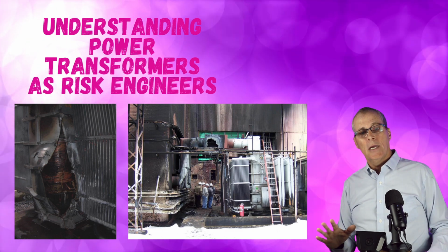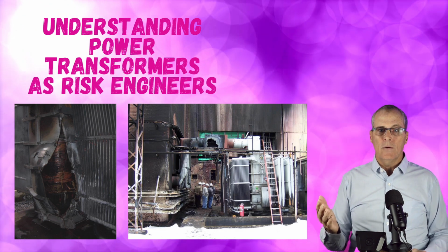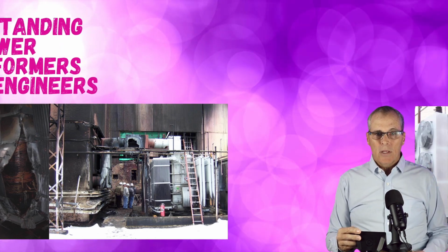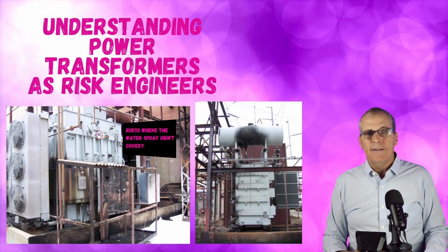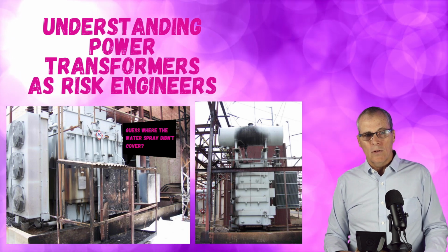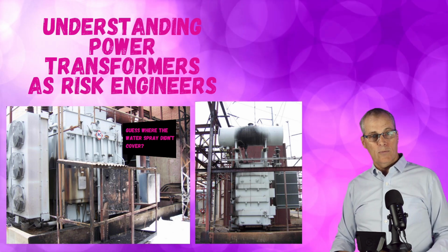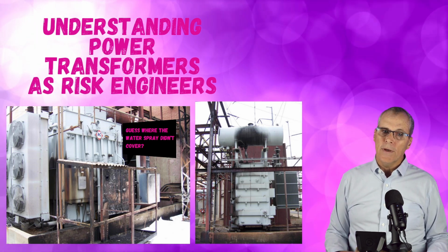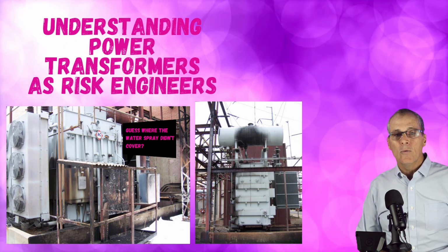But they're not trained well enough in that kind of firefighting, and I will admit that their training is don't shut off the protection. So this fire, you can see that we had deluge, and look closely at the picture on the left. You see that most of that transformer is protected, but guess where the water spray didn't cover? You see that little cabinet, it got scorched. We opened the cabinet up, all the wire in that was melted, but the rest of the transformer was fine.